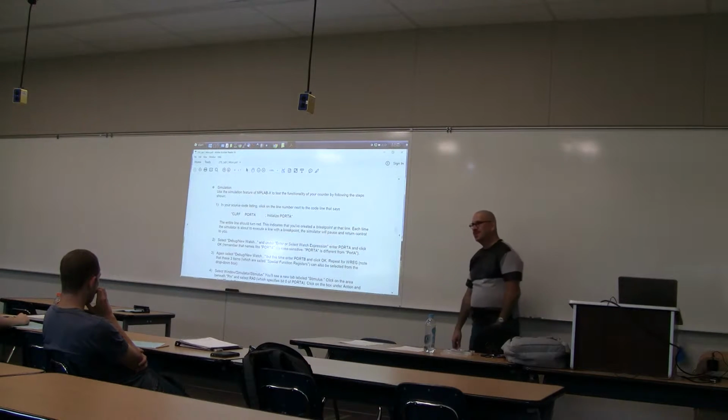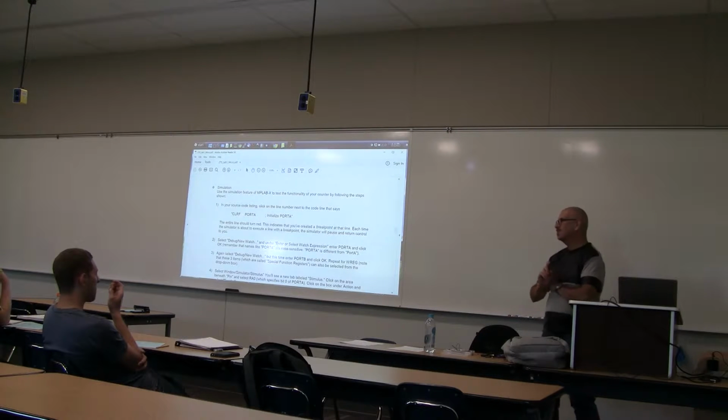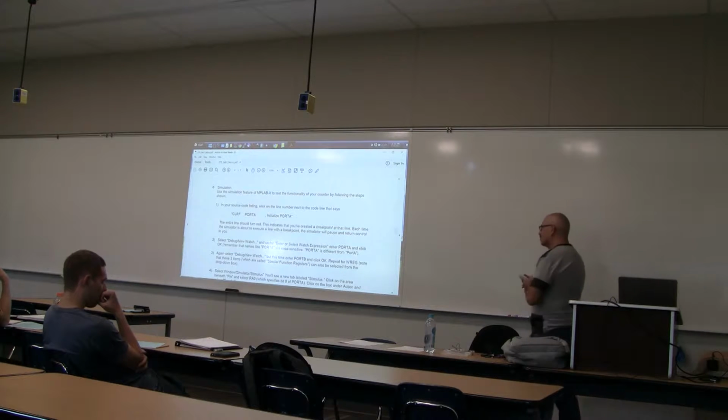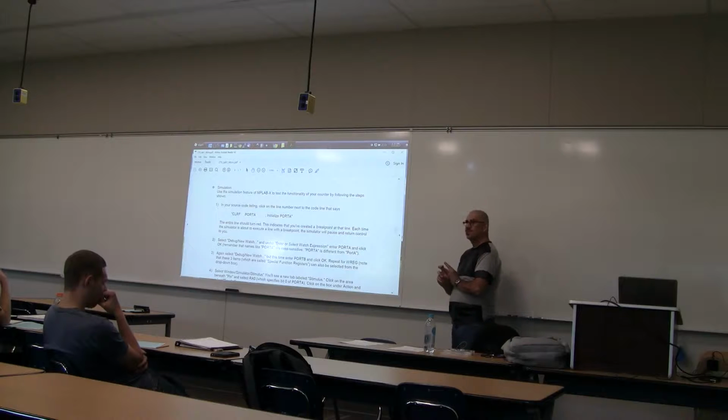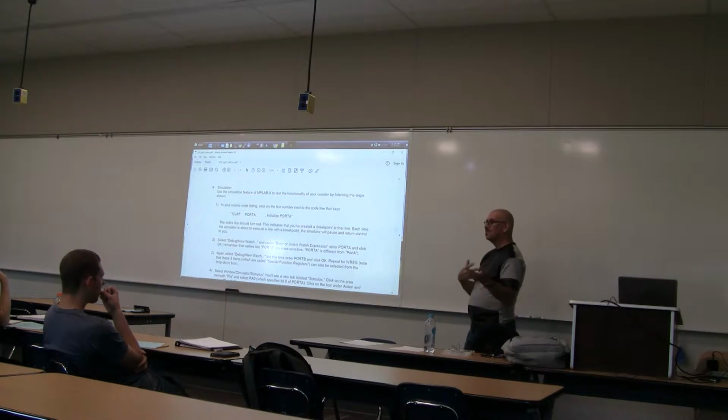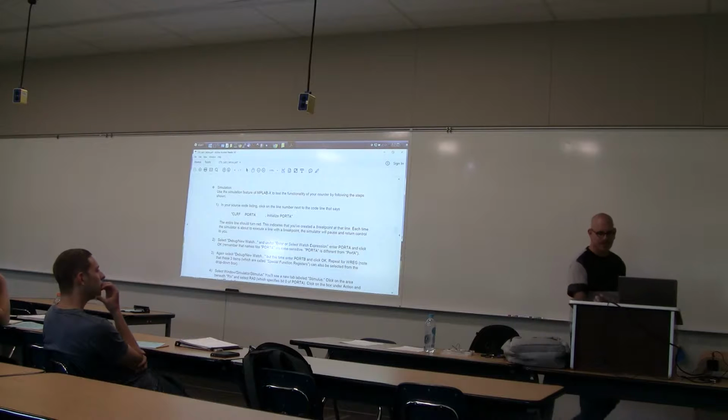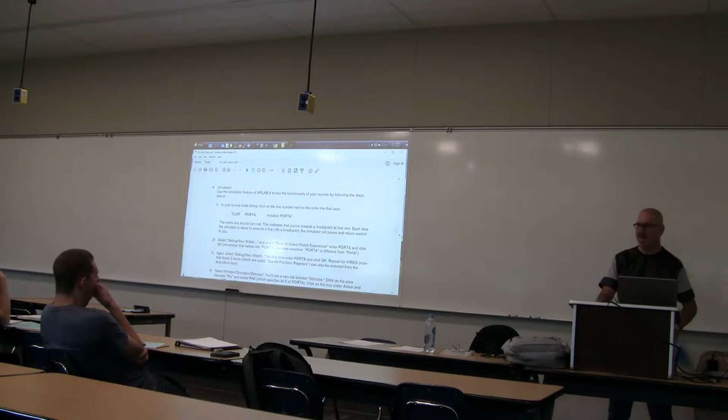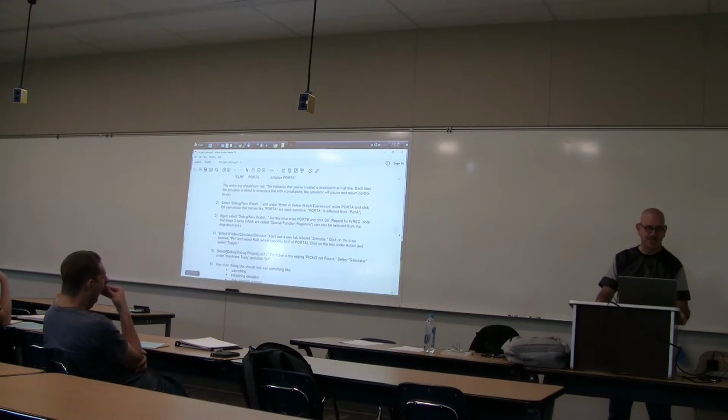And in the simulator we can say things like, show me the value of this memory location, or pretend that I put 5 volts on this pin. Okay? So we'll pretend that we're reading LEDs or sending switches in, and we can step through the code and watch what it does. And that's the first experiment in this lab, is doing all of this in simulation.